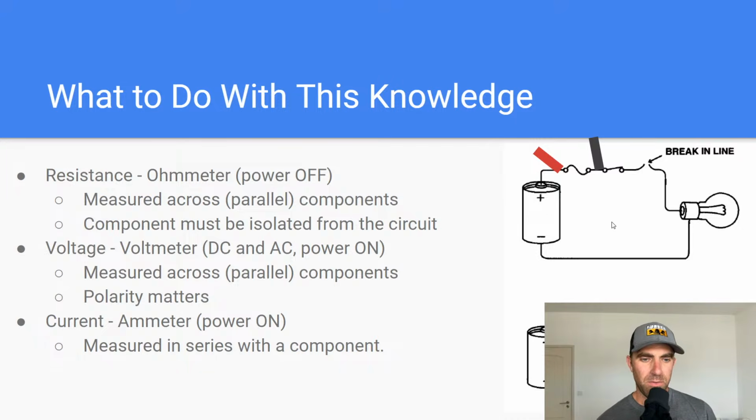But talking about voltage drops. If I wanted to know what the voltage of the system was at this fuse, for example, I would put my leads here. Power would be on the system, and then back to our Ohm's Law equation, if we didn't know what the voltage drop was across this fuse, we would take this measurement here, and you would be able to see what amount of voltage this fuse was consuming.